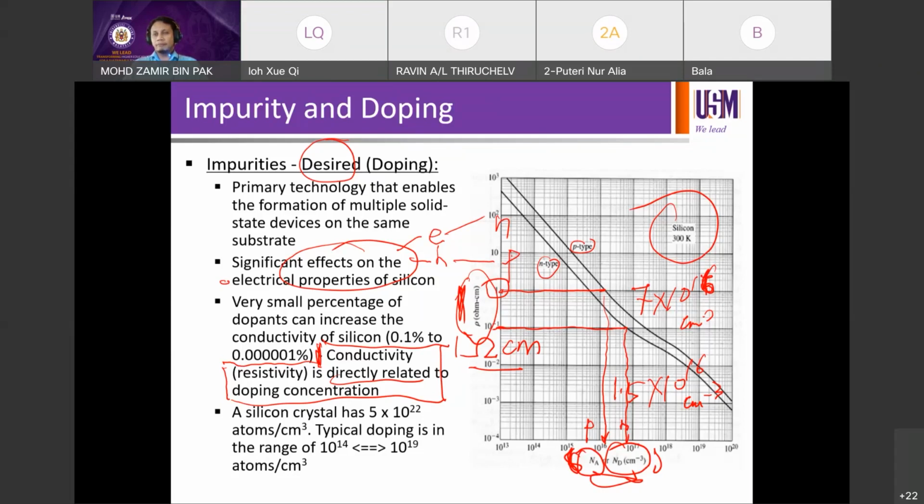So moderately doped is 15 to 18, is it? Normally people say moderately doped is about 15. You can say starting from 15, but typically people say about 16. But for lightly doped, moderately doped, and heavily doped, there is no clear-cut answer as far as the figure is concerned. Typically we say the region of lightly doped is 14 and below, and starting from 15 we can say moderately doped, up to about 17, and the moment you exceed that, from 18 onwards, you can say heavily doped.